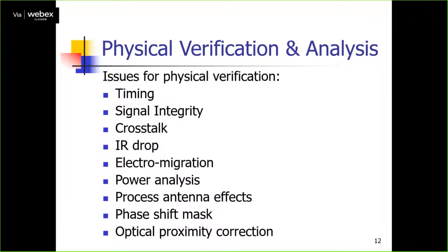Crosstalk is the one that occurs whenever you are routing parallel routes, either power or ground, power and ground, signal lines and power, signal lines and clock, and so on. This creates more crosstalk. Once crosstalk appears, a noise level is introduced to your system, and that noise goes on to reduce the signal strength of your system.